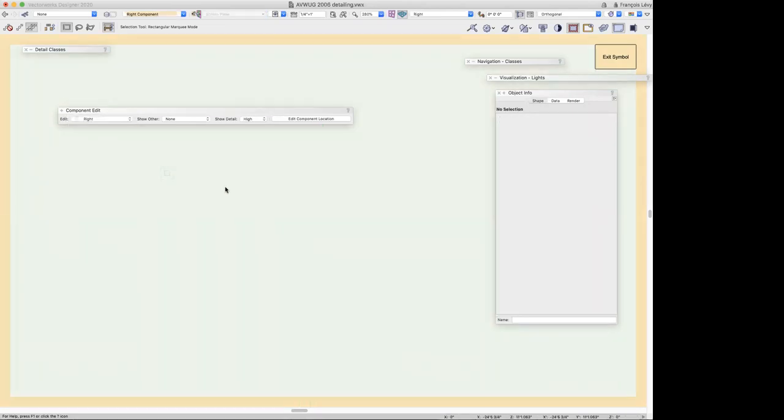And under the right view, you can see right now there's nothing there, right? But one of the things that I can do is show the 3D, so that gives me some context. So here's that 3D view sort of grayed out of this component. And I could just use that as a guide in order to make a two-dimensional drawing of that side view so that I would be able to substitute that 2D drawing whenever I had an exact side view of this symbol.